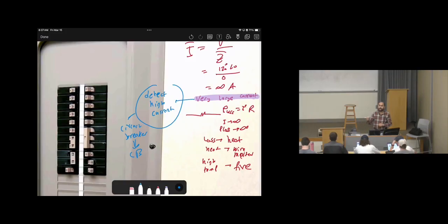There should be a time slot coordination for the breakers to trip. For example, let's assume that the circuit breaker should respond within roughly 5 milliseconds. If not, at 7 milliseconds, the main circuit breaker needs to take action. So we need to give it some time to take action. If not, I will take action, something like that. That's the overall idea about circuit breakers.